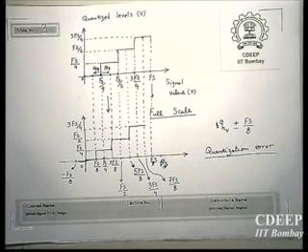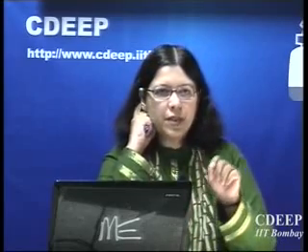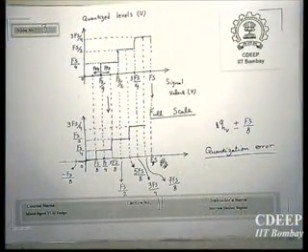When I sample my signal and give it to the switched capacitor, that is perfect because that signal is there. But now I'm quantizing it, so I'm artificially creating an error in the signal. That is called quantization error, and it is the difference between the signal level that I have here and the quantized level which is now assigned to the signal.